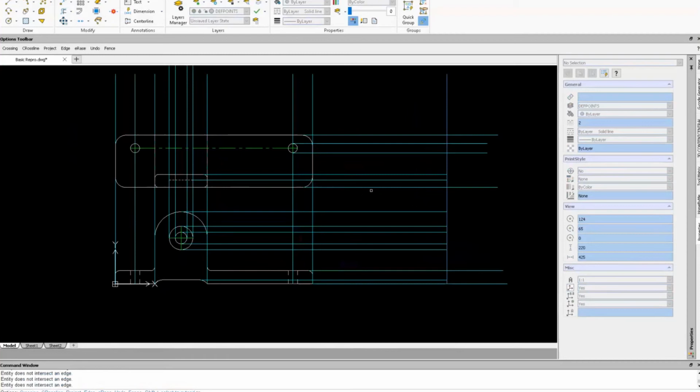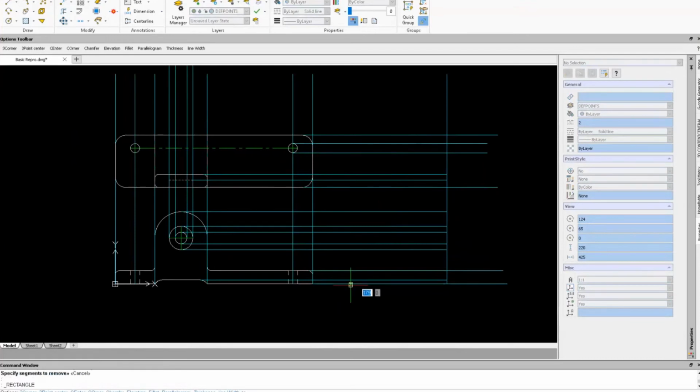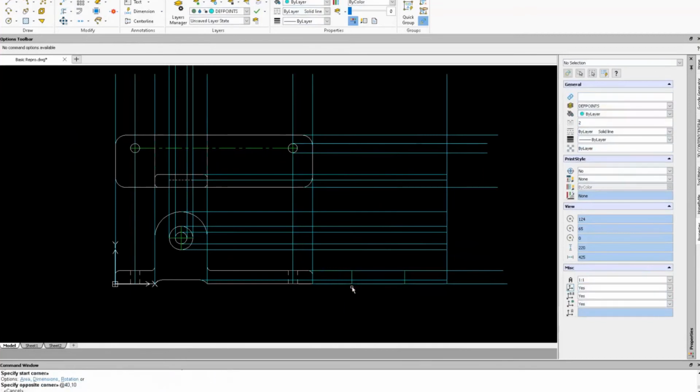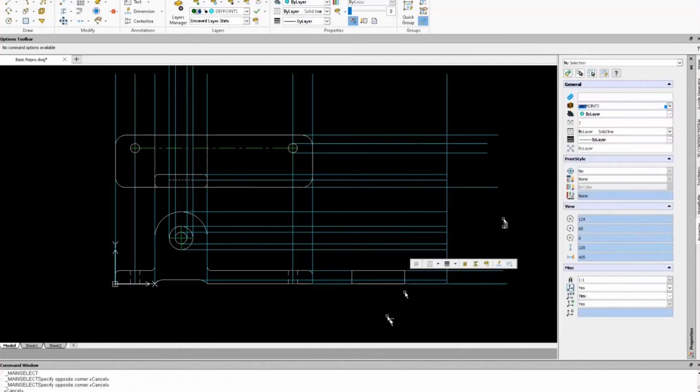So I'm going to go ahead and start my rectangle for the bottom base. I'm just going to start it over here because this is the only alignment I need. And then I'm going to go up 10, over 40, and up 10. So you'll notice that that rectangle was actually put on the def lines. I can move that if I want by just selecting it and moving it to the object layer. So see, now it's white.